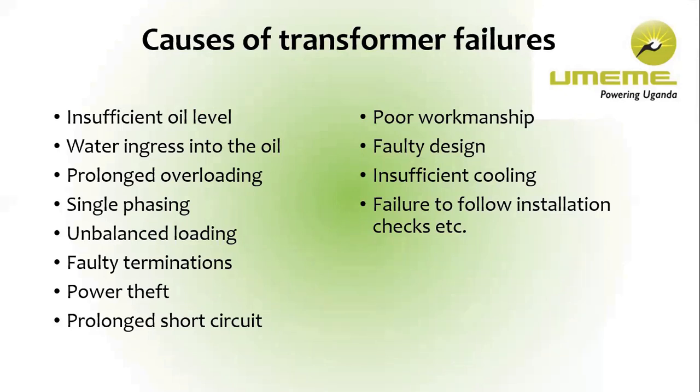What causes transformers to fail? Insufficient oil level, number 1. I told you the importance of oil in the transformer: for insulation and again for cooling. So when the level goes below the required level, you have to fill it. The moment the oil level is insufficient, the transformers are likely to have failures.